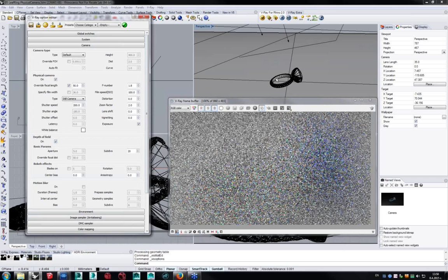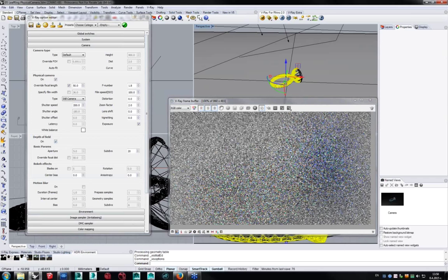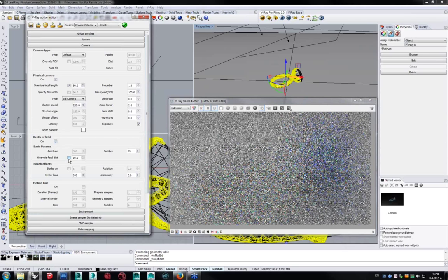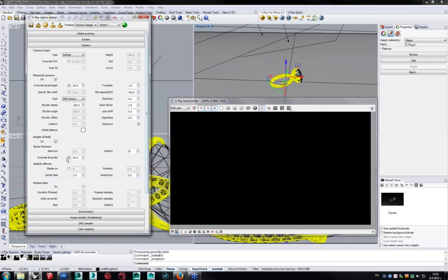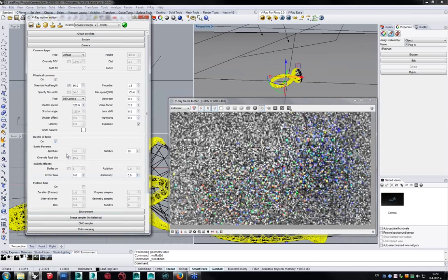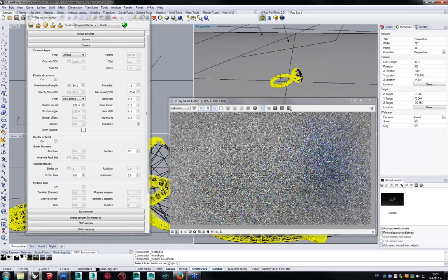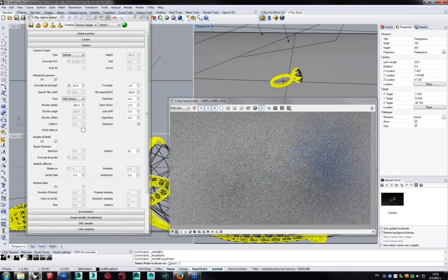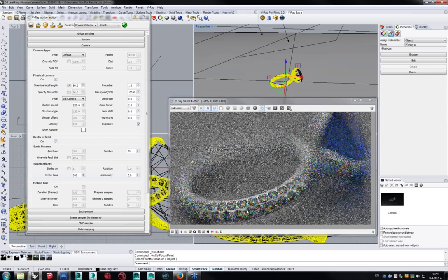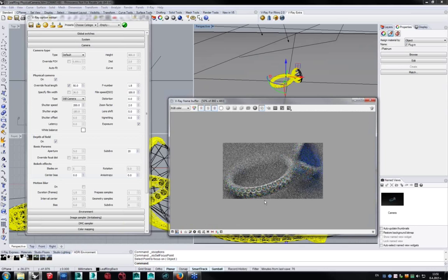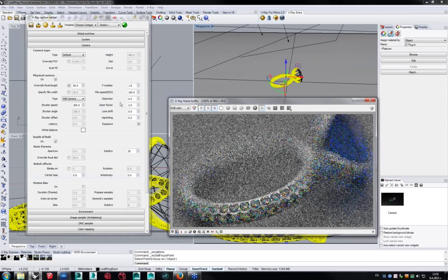and it's getting really, really blurry. Now one thing that we have added here, guys, is that you can override the focal distance. Of course, this is something where you need to guess the distance between where you're standing and where your geometry is. So what you can do is use this new button and just hit somewhere, but of course I need to enable the snapping, and there we go. The depth of field is so shallow that currently I'm having it only here.